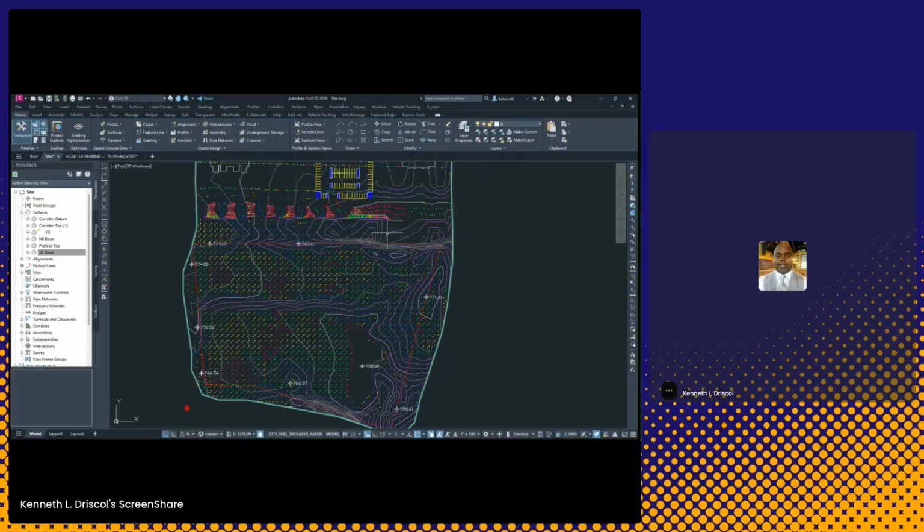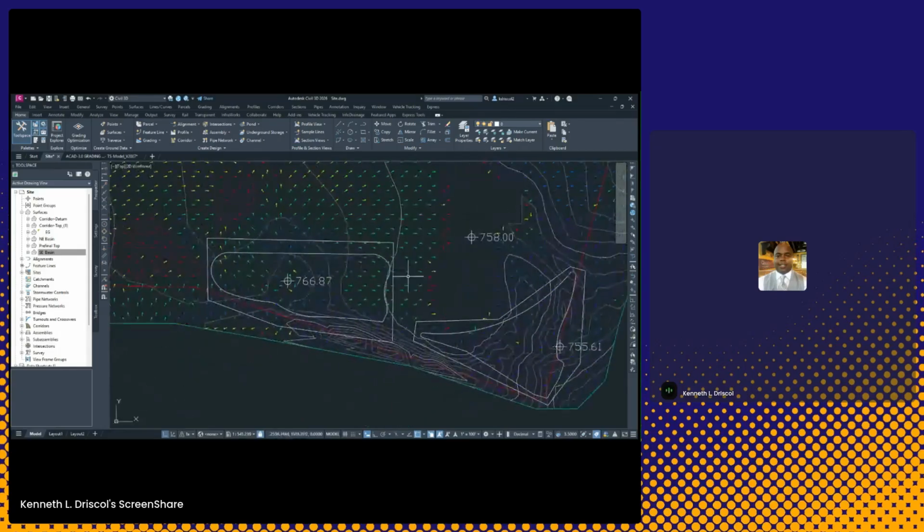From that, again, I want to determine where I'm going to put my detention basins. So really quick, I got just these polylines. And based upon these polylines, I got an area and the shape of the pond that I want to use, specifically based upon the number in terms of the volume that we're trying to achieve for these ponds. So one of the things that becomes critical is how much volume can we get in here, and how do we create this pond to determine it pretty quickly.